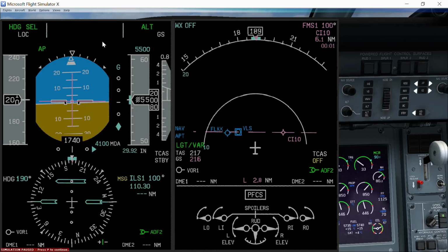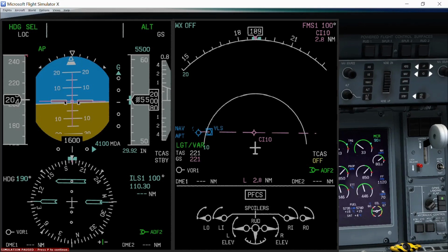Okay, so here we are on the last of the presentations, to understand how it would look if we intercepted the ILS glide slope from further out. What I've done here now, I have positioned the aircraft just perpendicular to the course intercept, where normally you intercept the localizer. So here you intercept the localizer if you reach this point, and thereafter when you turn, you'll intercept the glide slope from below rather.